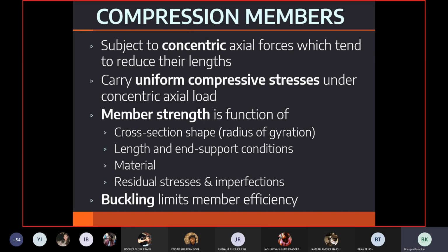In all our calculations we had the width and the thickness of the member. If it is an angle member, then we had the gross area and the net area. So it depends upon the cross section dimensions of the member. Then in all our formulae, we had either the yield stress or the ultimate stress. So it depends upon the material properties as well.